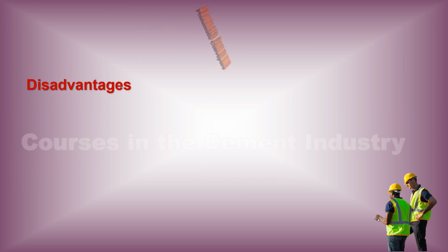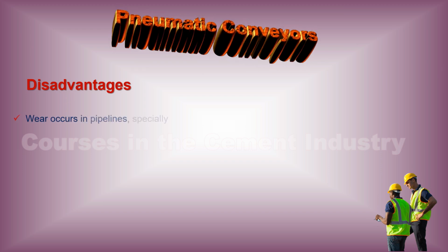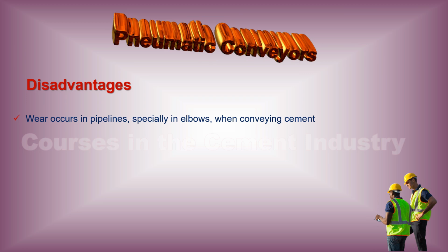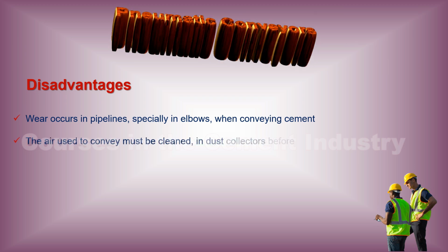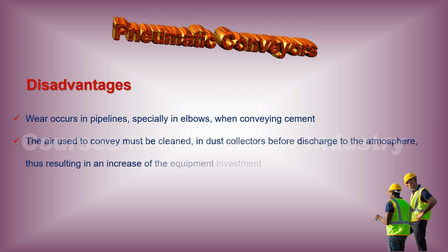Disadvantages of pneumatic conveyors. 1. Wear occurs in pipelines, especially in elbows, when conveying cement. 2. The air used to convey must be cleaned in dust collectors before discharge to the atmosphere, thus resulting in an increase of the equipment investment.